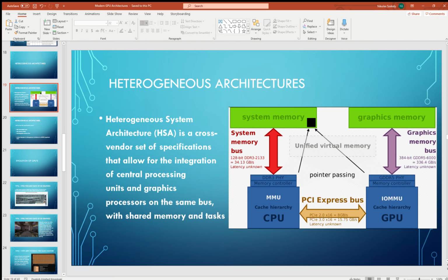HSA allows programs to use graphics processors for floating point calculations without separate memory scheduling. HSA creates an improved processor design that exposes the benefits and capabilities of mainstream programmable compute elements working together seamlessly. With HSA, applications can create data structures in a single unified address space and can initiate work items on the hardware most appropriate for a given task. Sharing data between compute elements is as simple as sending a pointer. Multiple compute tasks can work on the same coherent memory regions, utilizing barriers and atomic memory operations as needed to maintain data synchronization.